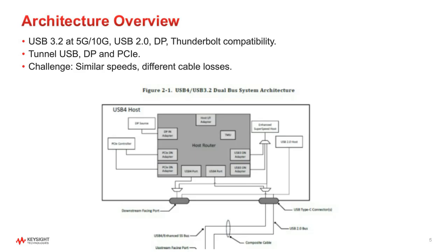And one of the questions we get asked quite often is, well, what if I just tested the port for, let's say, Thunderbolt 3 at 20.625, which is the highest rate we know of being put out through the Type-C connector? If I test at 20.625, then perhaps I don't need to test USB 2 at 480 megabits. And the answer is no, not because of the bit rate, but because they have different use cases. The cable loss models for USB 4 at 20 gig or Thunderbolt 3 at 20.6 are completely different from a USB 2 cable, hence the need to test all these different standards.